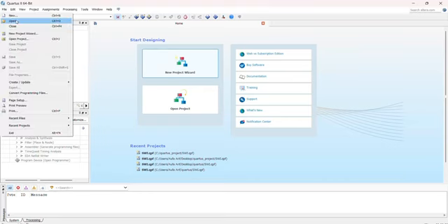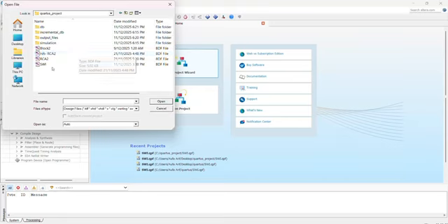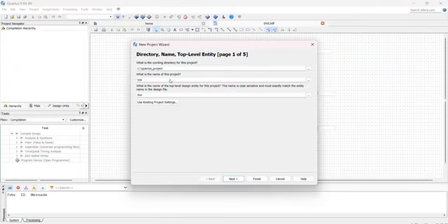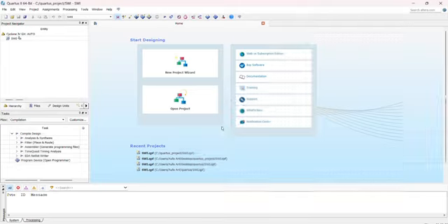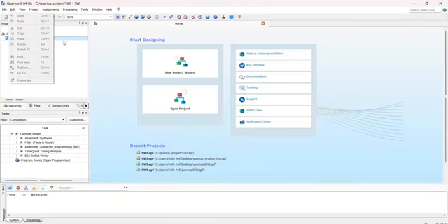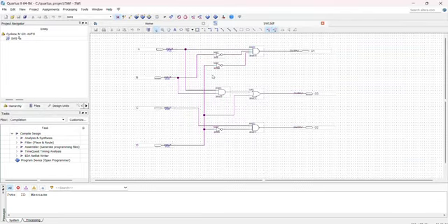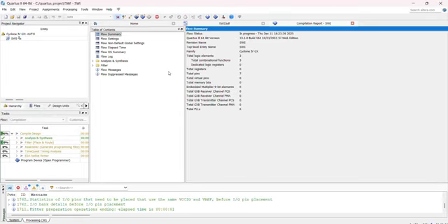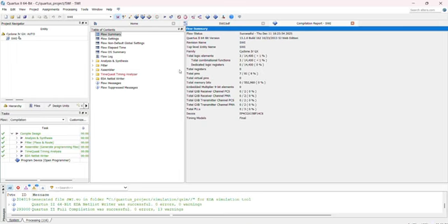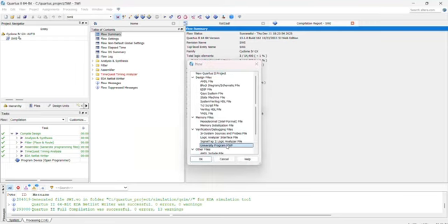After we have simulated both our logic configurations, we can also create a timing diagram to verify our outputs. We can also do this in Quartus software. Creating a timing diagram for logic gates in Quartus II is typically done through the simulation process using the vector waveform file, VWF. This VWF allows you to define the input signals over time and then visualize the resulting output signals, creating the diagram.